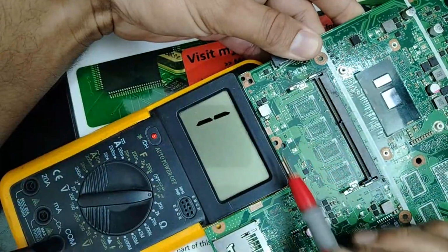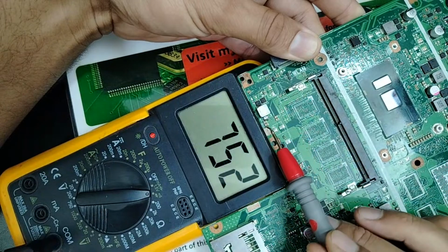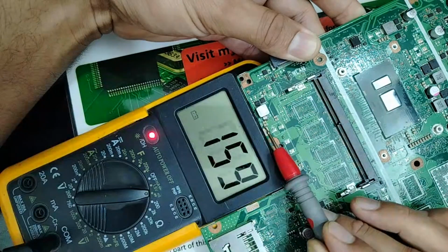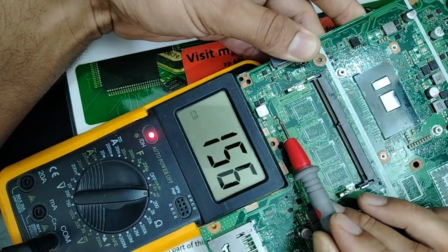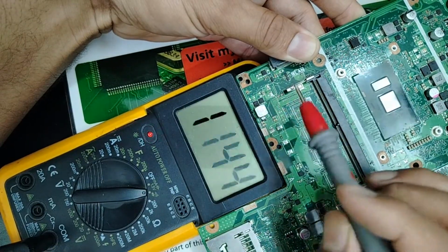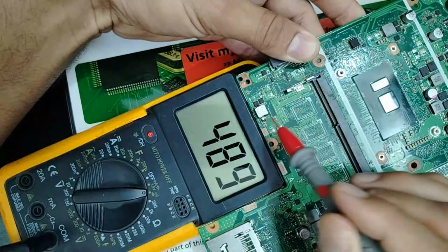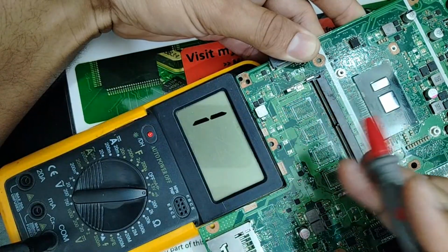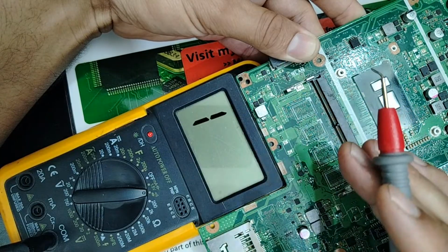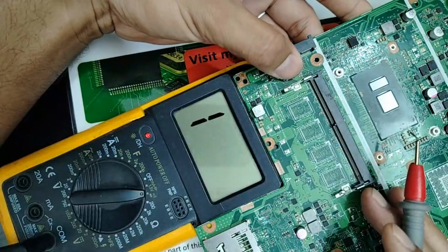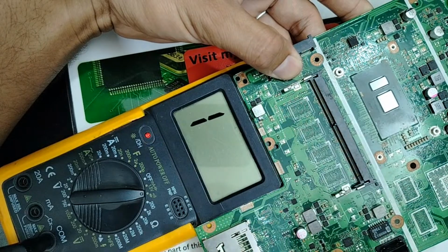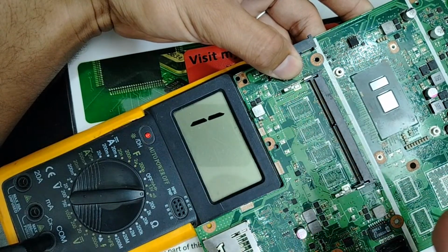Okay, and for this circuit, we have the output here, we have capacitors. All these capacitors also are shorted on both sides. All components here are shorted. Even MOSFETs are shorted, as you can see. Everything is shorted in this circuit. So how can we find out the short without using the thermal camera, without using the voltage injector, without using anything, just the multimeter and the knowledge and the process?